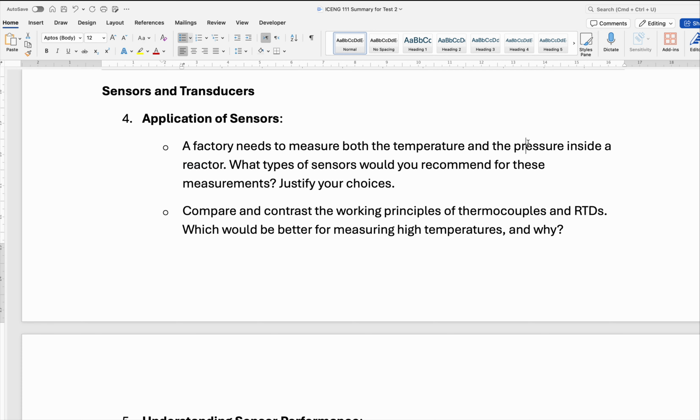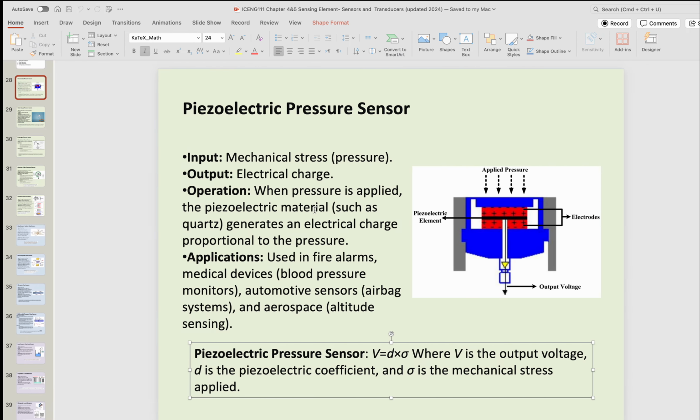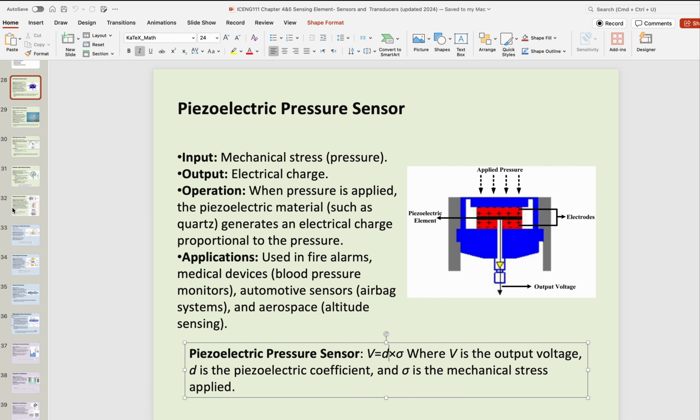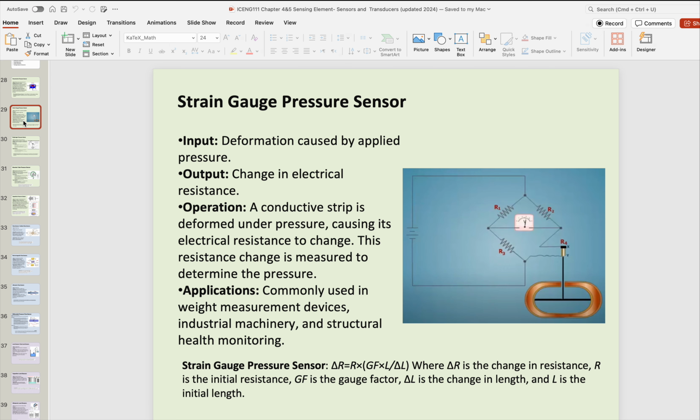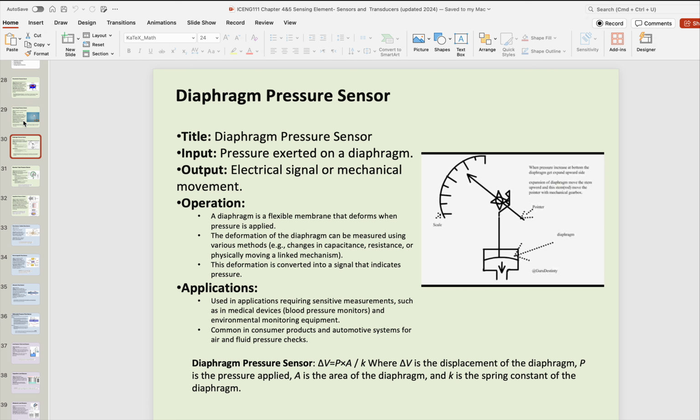And for the pressure sensor, there are many kinds of sensors that you can use, but maybe they suffer from hysteresis, and this could be a problem. So we have the piezoelectric sensor, that's a good one, but we have a reaction, and I don't want it to be in contact with what I have. Maybe the strain gauge, somehow it is possible.